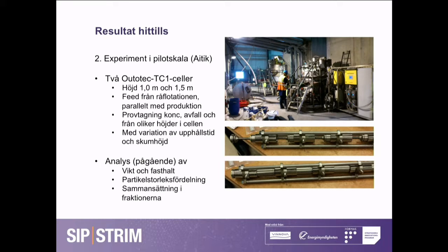So we did in that case tests in the rougher flotation and also sampled not only the products, so the concentrate and the waste flows, but also within the cells at different heights, in order to get a vertical profile.